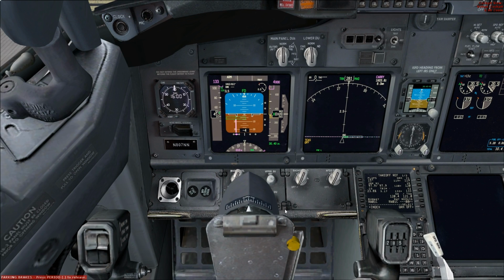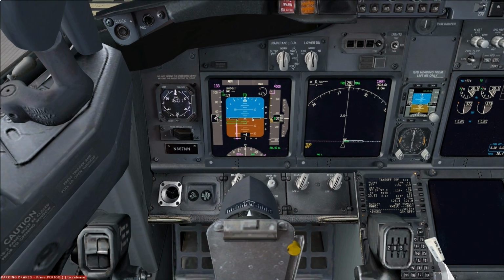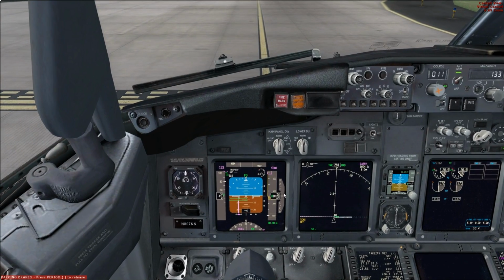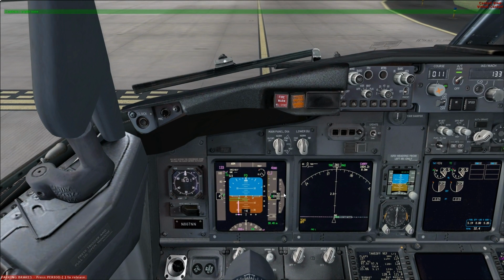Now, the way I understand the predictive wind shear system to work is that when the aircraft is at 1200 feet or below above the ground, the predictive wind shear system works with the weather radar, and instead of the weather radar scanning from left to right as it normally does, it starts to scan in a figure 8 pattern turned on its side. So it sweeps from top left to bottom right, to top right to bottom left, and back to top left, and it repeats.